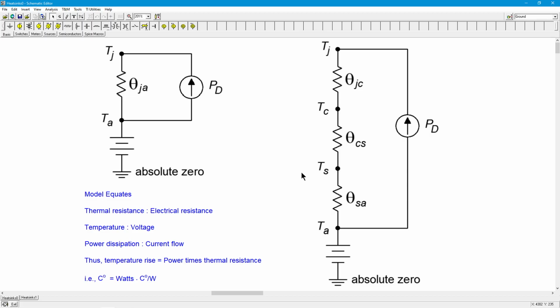Think of this as an electrical circuit. Hey, current's going to take the path of least resistance. So if this is a lower resistance, guess what? By our Ohm's law, thermal version of Ohm's law, that should be a smaller temperature rise. Right? That's the whole trick. You're basically sort of short-circuiting the case with the heat sink because it can dump heat more efficiently.